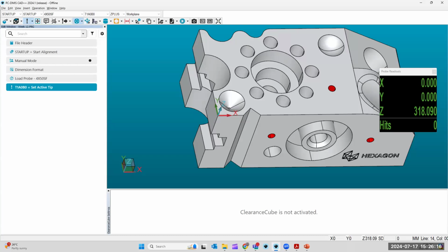Right. So that's the point of an alignment. But what if we could just do a plane, plane, plane alignment? 3, 3, 3 points. And we could do it that way. Or we can do 3 points, 2 points, and 1 point. Right. I can't monitor the chat necessarily at the same time, but Arif, yes, that's right. So we could save time and operator inconvenience and potential errors by doing a 2D alignment. Yes, it does cost a little bit more time in programming. It's worth it in the long run.